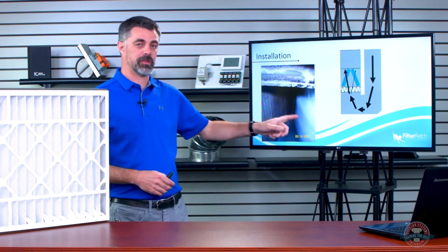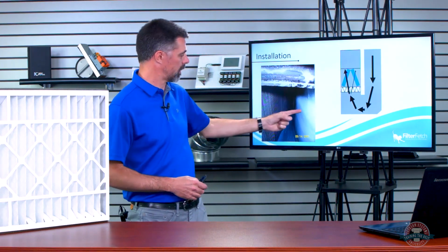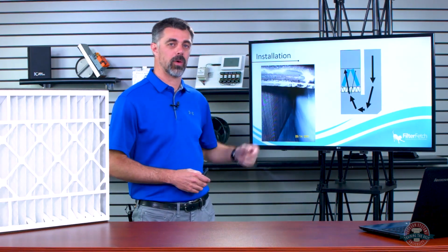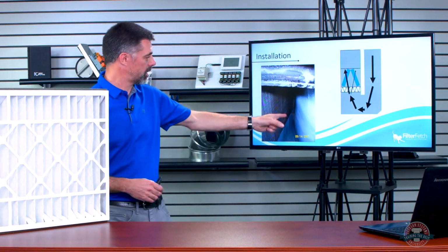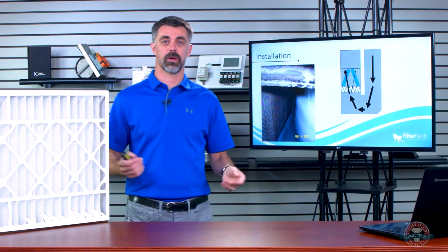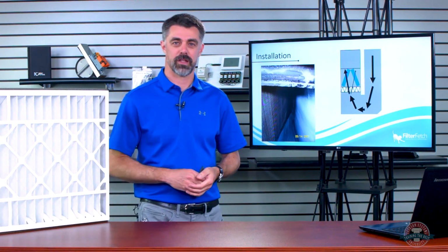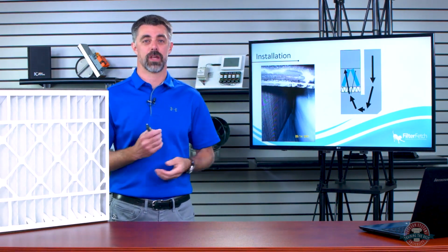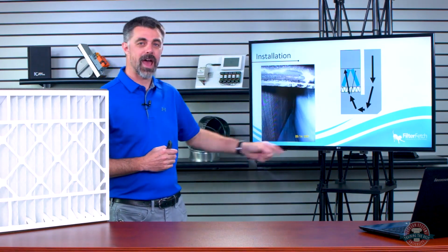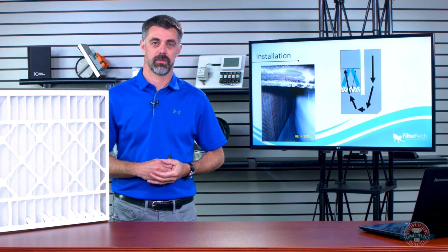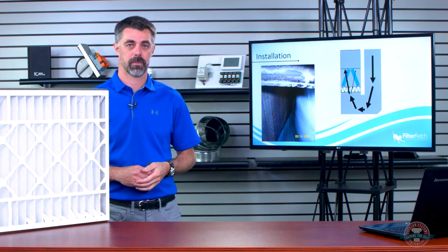Where it was sitting inside, I could get the filter door off because the filter sat right here, but I couldn't get my head around to see this side of the coil without moving some stuff because of where the door was on the front of it. So I looked up inside and I saw a nice clean coil. I said, hey, great, the coil's clean. I never could get it quite working right. I scratched my head. I went back inside to double check myself, and I got my head farther around in there, and lo and behold, half of that coil was frozen. Frozen solid over here, where this half is perfectly clean.